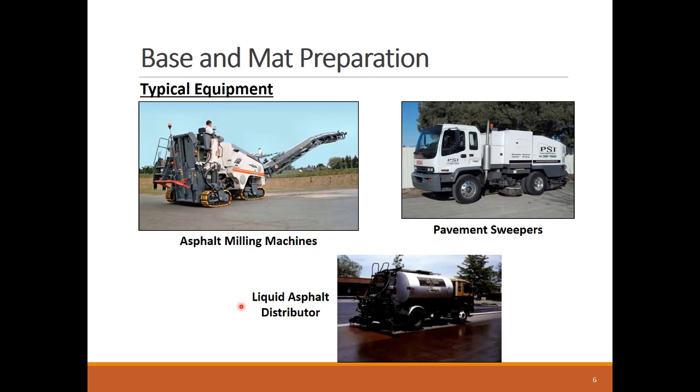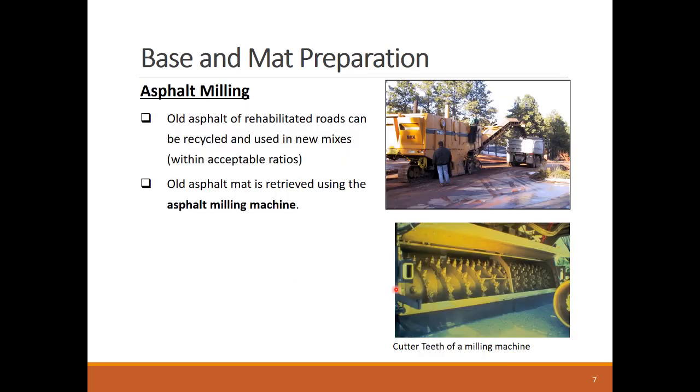The surface that will receive the asphalt needs to be prepared by removing any old pavement mat, sweeping any dirt or unwanted objects, and spraying the liquid asphalt. Over its life cycle, asphalt pavements get minor treatments for potholes and cracks. Over the years, these minor treatments lose effectiveness, and more extensive rehabilitation work needs to be done by removing the top wearing course of the asphalt and placing a new one. However, the good thing about asphalt is that it is recyclable to some extent.